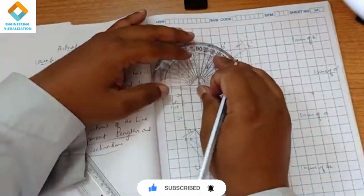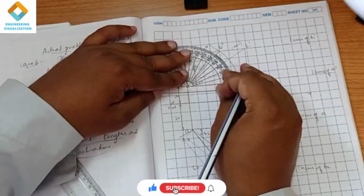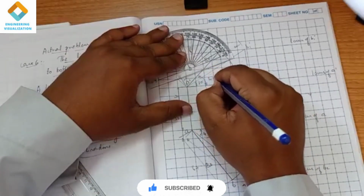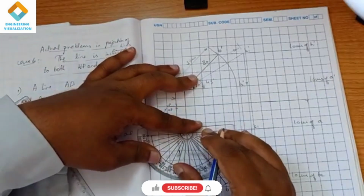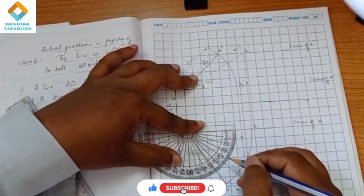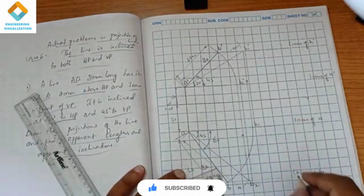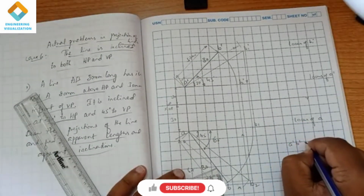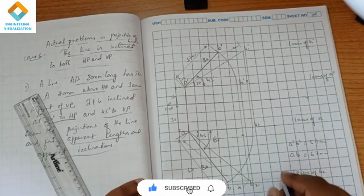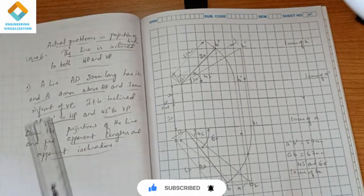And the apparent inclinations we also have to find out. Here we have 45 degrees, and for this one we have around 50 to 60 degrees. So we are getting the apparent lengths A dash B dash as 57 mm and AB as 67 mm, and the angles as 45 degrees and 60 degrees. Okay, so this completes the problem.